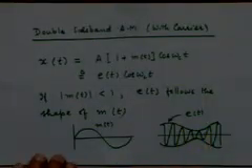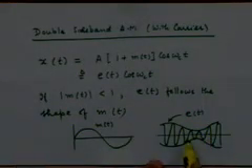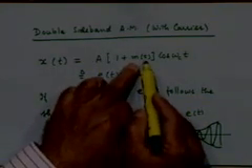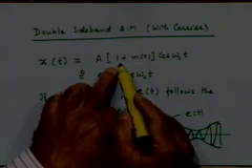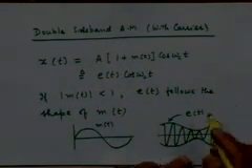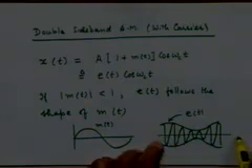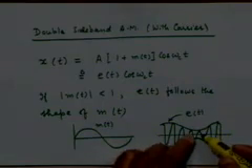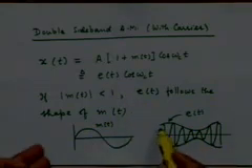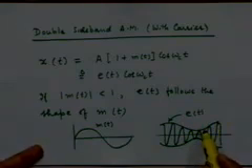With respect to this modulation, you can see that depending on the relative value of modulus of mt with respect to 1, you can have a situation where this envelope is fairly above the time axis, or it can even touch the time axis. For example, if the largest value of mt is equal to 1, then the envelope will even touch the x-axis or the time axis.